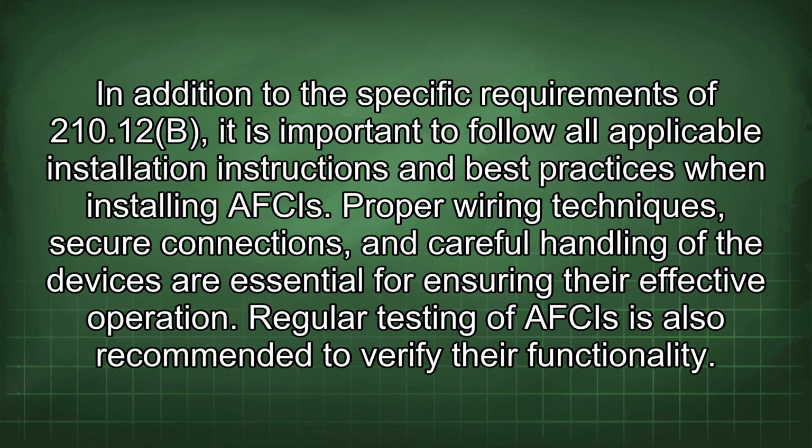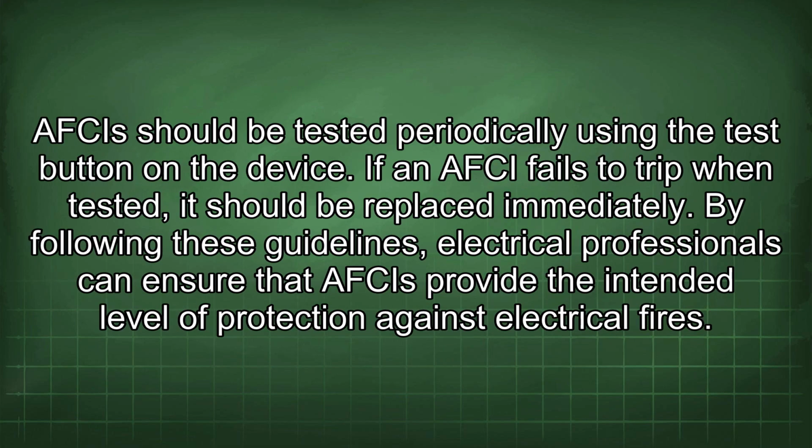In addition to the specific requirements of 210.12b, it is important to follow all applicable installation instructions and best practices when installing AFCIs. Proper wiring techniques, secure connections, and careful handling of the devices are essential for ensuring their effective operation. Regular testing of AFCIs is also recommended to verify their functionality. AFCIs should be tested periodically using the test button on the device. If an AFCI fails to trip when tested, it should be replaced immediately. By following these guidelines, electrical professionals can ensure that AFCIs provide the intended level of protection against electrical fires.